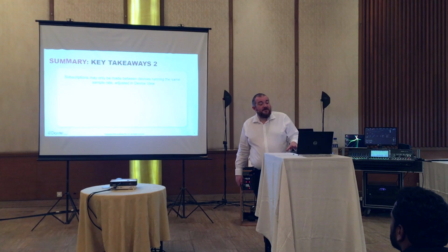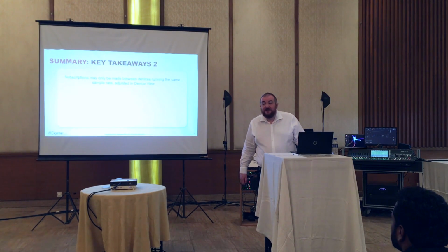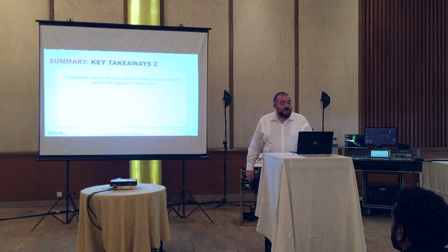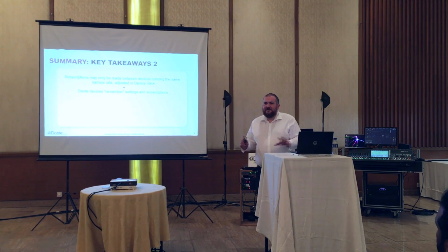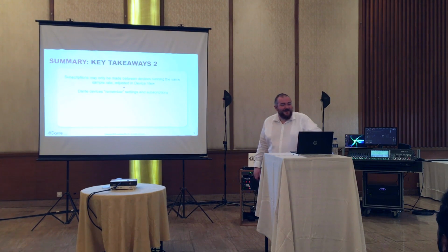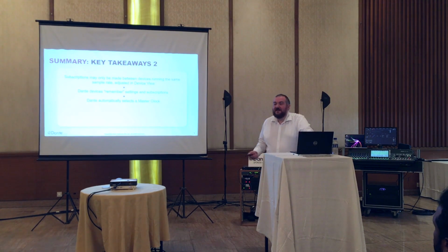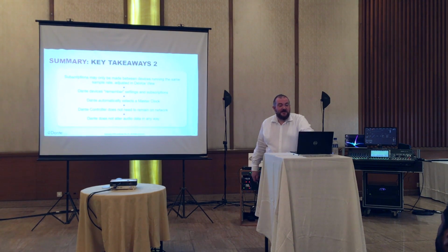So, of course, subscriptions can only be made between devices running the same sample rate or media type. Now we have video, and we can adjust this in device view. You can't adjust an audio device to be a video device. We haven't done that yet. Devices remember settings and subscriptions, and of course Dante automatically selects a master clock. And Dante Controller does not need to remain on the network for this control to happen.